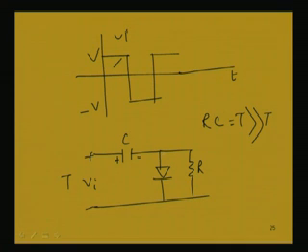This is an ideal diode, there is no drop, and it will be like a short circuit. It will be conducting through this part. So, this capacitance will be charged to a voltage of V, and as the charging time constant is almost 0, because the diode has a very negligible resistance, and in this case we have neglected that resistance. So, the charging time is almost 0, and instantly it will be charged to a positive voltage V when it is charged to the peak value.